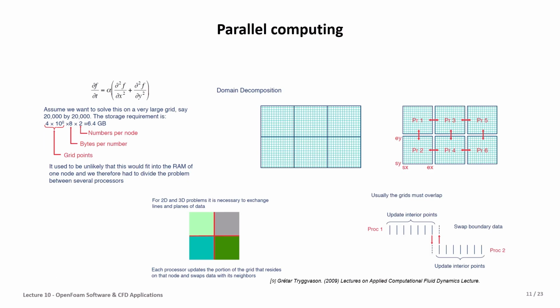To make parallel computing and HPC applications for CFD, this is a reminder of what we presented in the previous lecture on how parallel computing works for the specific domain of the problem. We need to make a decomposition of the problem, and here we can see the amount of storage which is required, and we also talked about the overlap between the subdomains, which is important because the boundary data need to be interchanged in this area, especially when we have an unsteady problem.